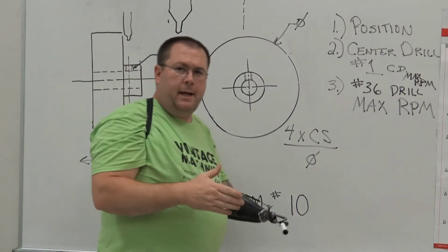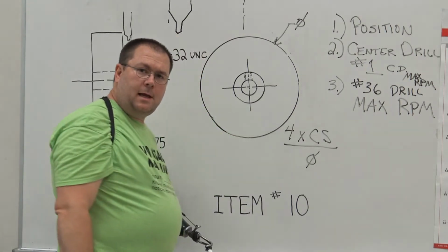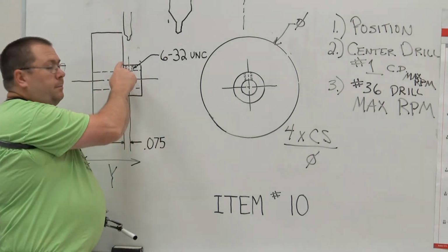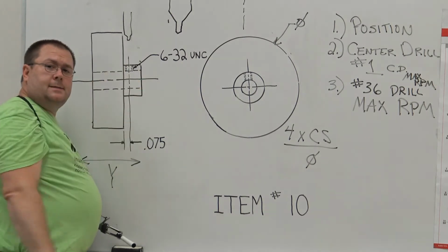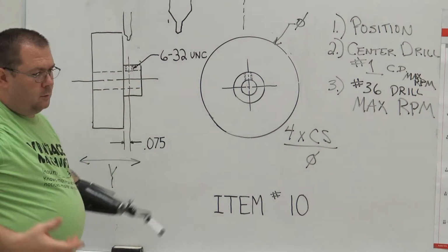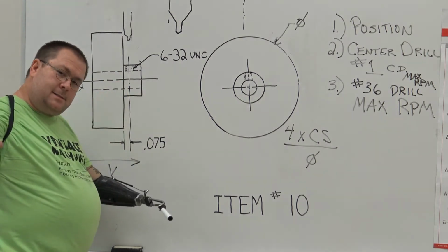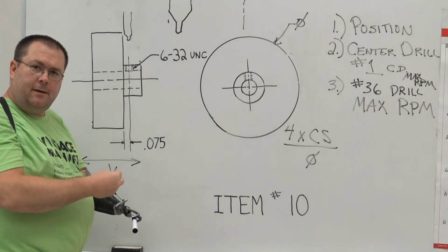Whenever I do any cutting operation, what forms? Well, what forms is a burr, B-U-R-R, a burr. Well, there's going to be burrs up here on the top edge, and there'll be a burr inside the hole. Why do I bring that up? Well, it matters inside the hole because I still want that 3/16 shaft to slide nice and easy down through.